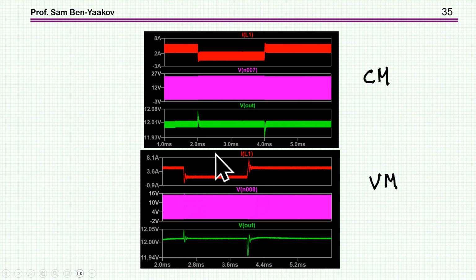But when I compare the peaks here and here for the two injections, that is loading this positive current and negative current, you see that the magnitude is not much different. In fact, in the current mode, a little bit higher than that. This is because the peak is primarily due to the ESR, which has nothing to do with the current mode or the voltage mode. This is just the nonlinear behavior of the system.